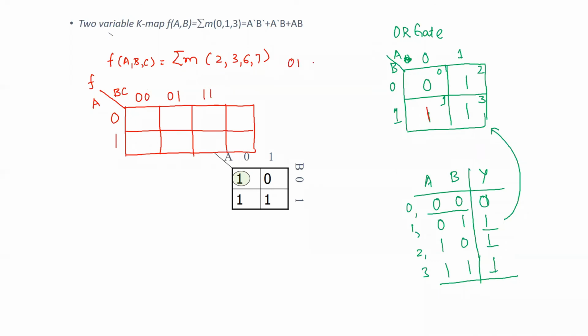If the transition is from 01 to 10, both bits are changing, and we know that we are using Gray code here, so only one bit will change. From 01 it will become 11, and from 11 it will become 10. Once again: 00, 01, and 11.